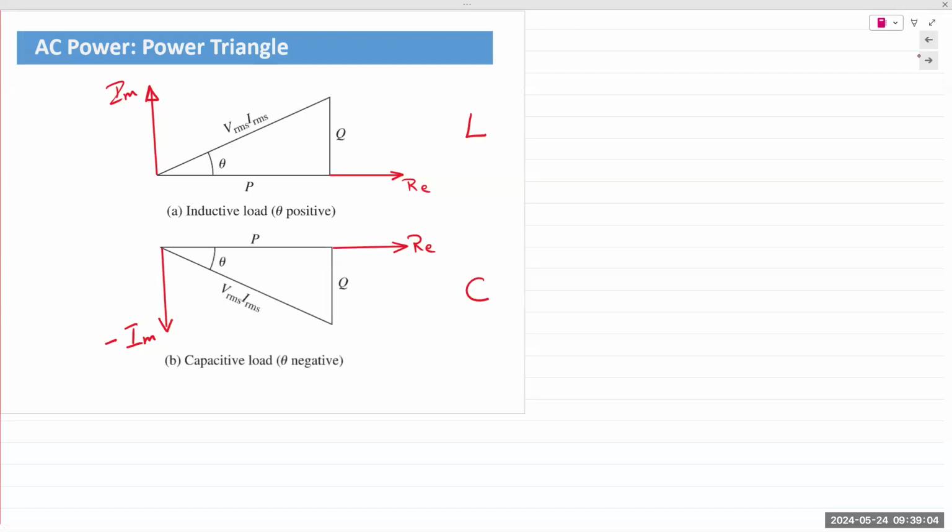Again, at the beginning, I said a capacitor behaves exactly the opposite of an inductor. Goes back to the impedance of a capacitor being negative with an angle of -90. Impedance of an inductor is +90. Impedance of a capacitor is -90. And so that allows us to balance out the energy requirements of an inductive load with a simple capacitor.